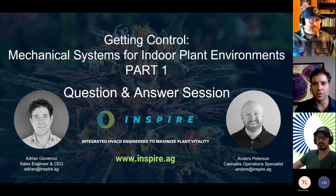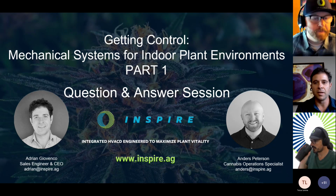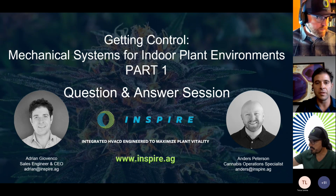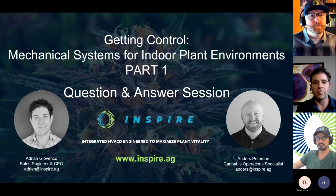Yeah, that's a really great question. I can jump in on that one if you like, Anders. In general, you want technicians that know and understand refrigeration systems and packaged or split systems, particularly ones that have hot gas reheat in them, and modulation, such as modulating compressors and modulating hot gas reheat valves. Obviously, that expertise is required, and I would use that as some of the early criteria when you're vetting a particular maintenance contractor.